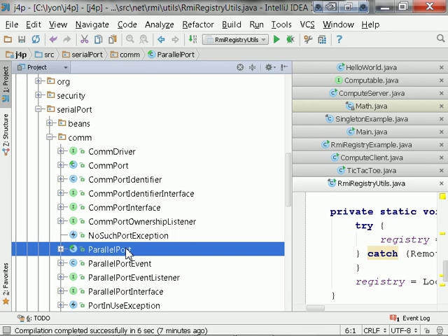But we also have access to those through the same API. And what can you do with that? Well, you can take an LED and plug it into one of the pins. You can take the other pin and put it into the ground, and you can turn the LED on. There's actually more practical things you can do with it, but that's one of the things. You can individually control the bits coming out from the parallel port, and it's a relatively high-speed interface. So that's kind of neat.